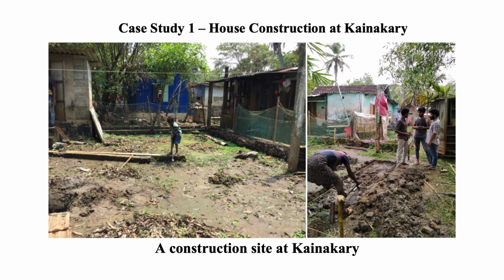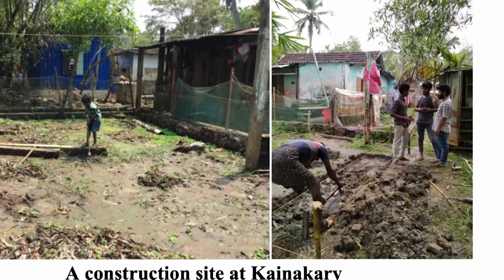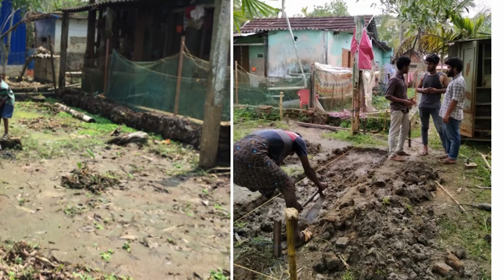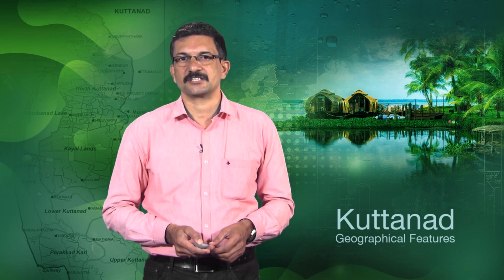A small trench was taken for the foundation first of all. As you can see in the second picture on the screen, a small trench is taken to have sufficient anchorage for the structure. But when the trench was taken, as expected, the soil had a very poor bearing capacity, very soft. The soil available there also had sandy content, which was a good thing, not clay content alone. So, the excavation was taken just like that, and then we proposed soil stabilization techniques.